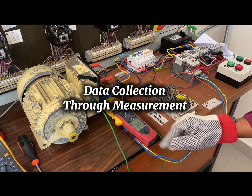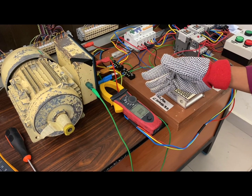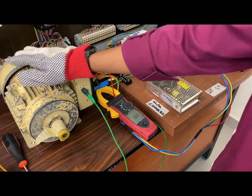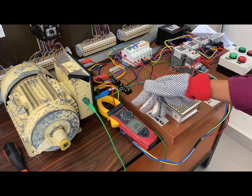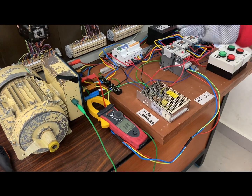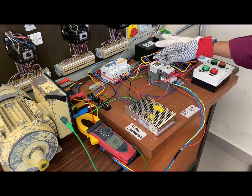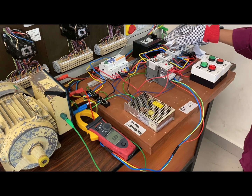So for the first measurement, we need to focus on the reading of inrush current, which is in the ammeter, because after the motor starts, for 1 second, the inrush current value will show up, and then after the motor rotates, the current of the star will show, and then the delta current will show.